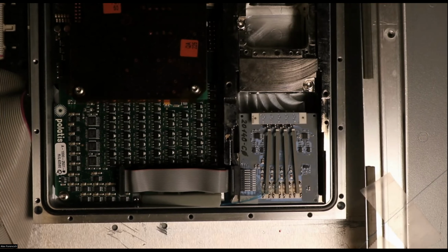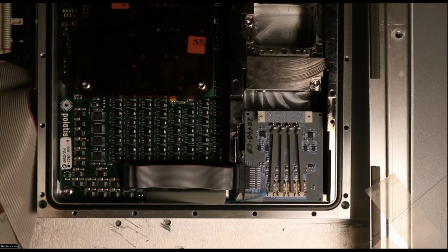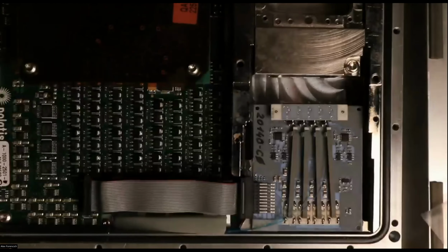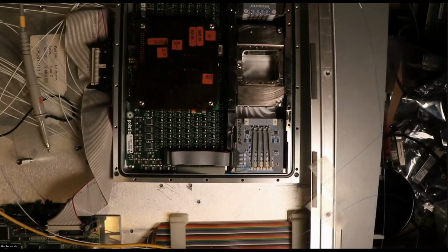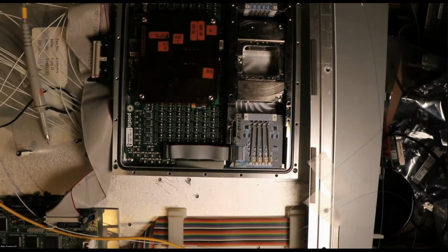So okay, that works. So yeah, I got that and the fiber adapters off of Amazon for hooking this thing up and seeing if there's any signs of life. And unfortunately, there was some, but if you take port 1 to port 17, which is just kind of 1 to 1 through the switch, that works. But if I take 1 to 18, the insertion loss goes up by a lot. If I go 1 to 19, there's like no light going through at all.